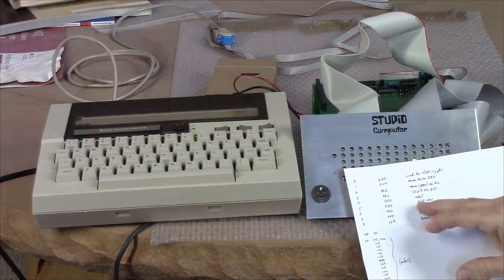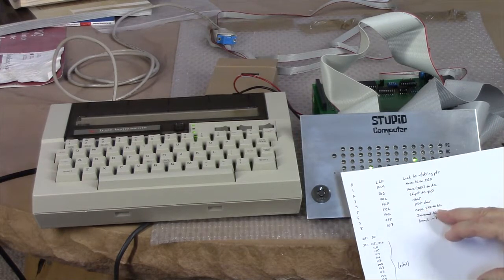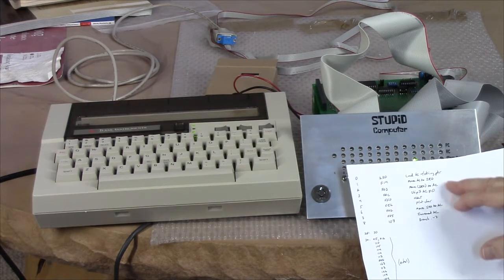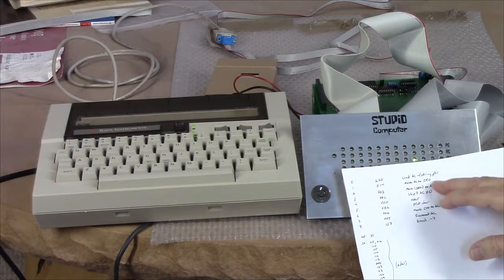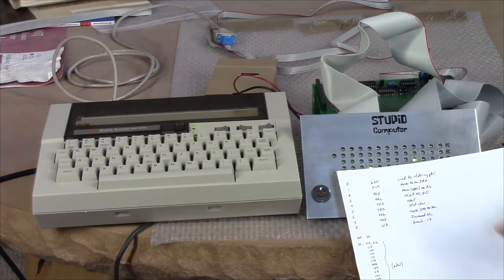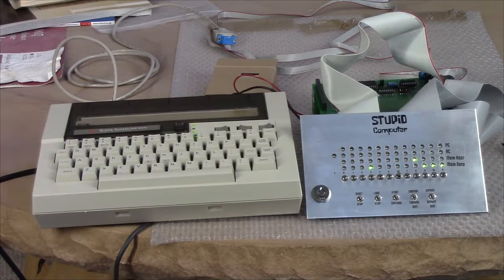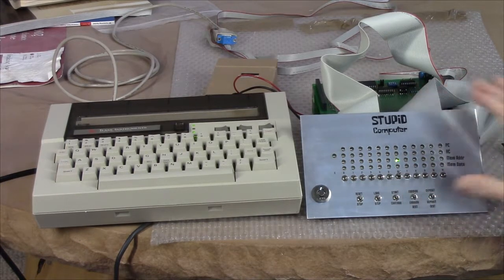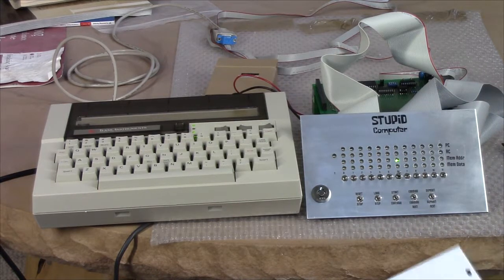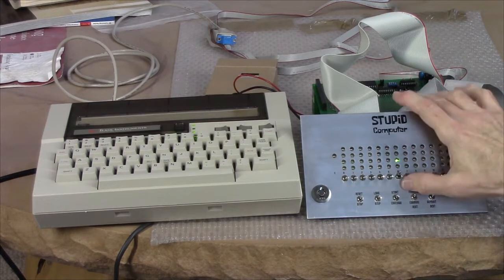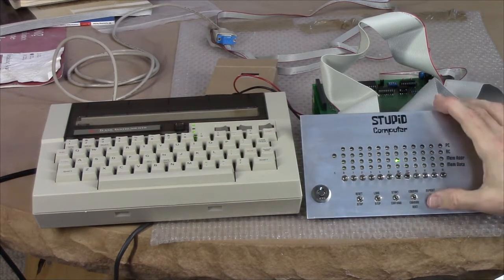If it's 0, it'll halt, otherwise it prints the character, moves the indirect register back to the accumulator, increments it, and branches back up to location 1 here, which moves the accumulator into the indirect register, and just keeps going until it hits the null. So location 20 has the address of the string, and I'm putting the string at 30